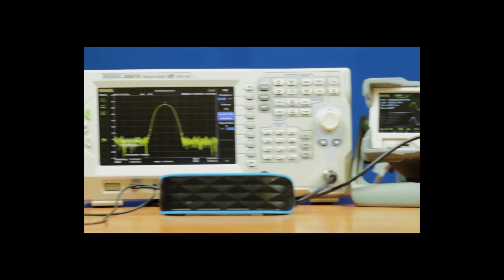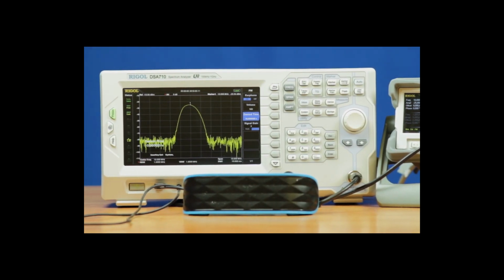So it's able to immediately, in its demod mode, demodulate that FM right back into the audio source that's generating it. And here we switch our signal gain and our volume settings to optimize that. But again, a great reason why FM works really great for this sort of application is because whether you have cables connected like this or antennas, the frequency changes are easy to pick up.